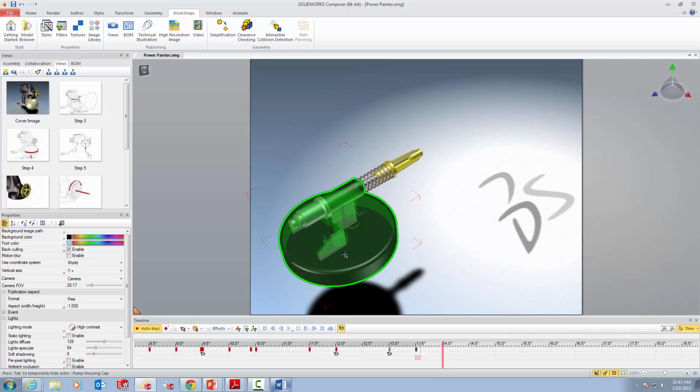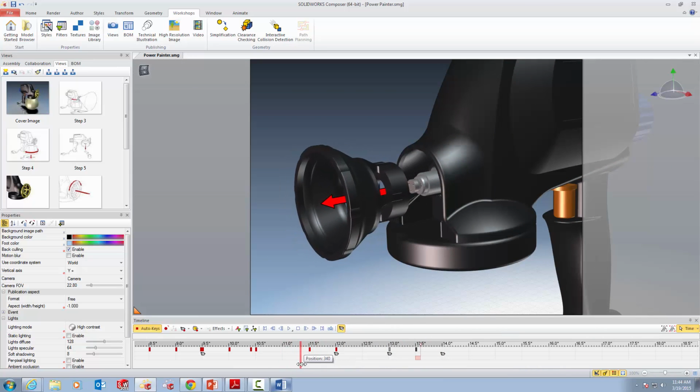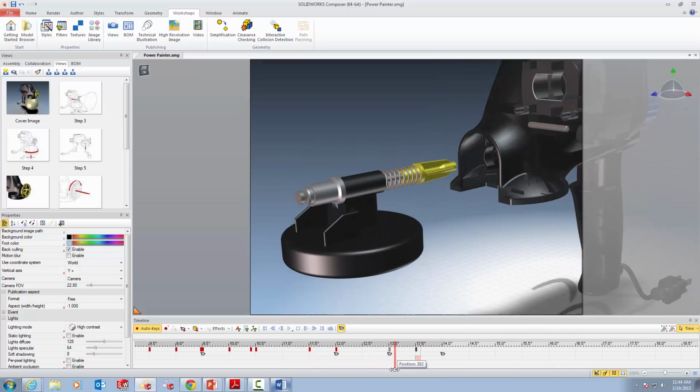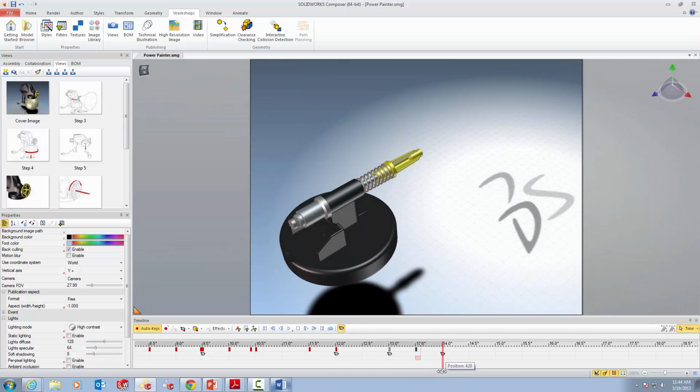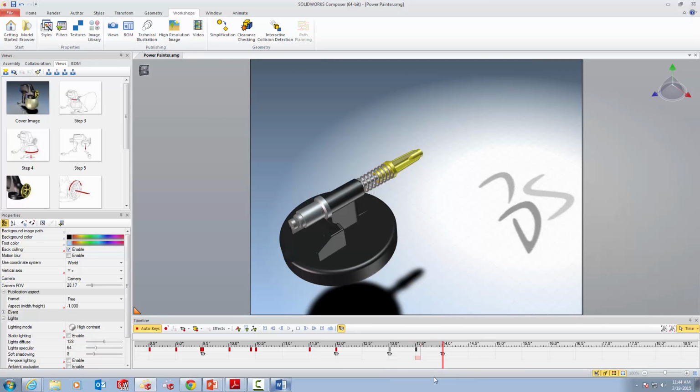And now I'm going to actually select this tool right here called Set Camera Key. Now what Set Camera Key does is it makes a note of its new location. Now what's great about this animation tool is as long as I have this option right here called Camera Play Mode on, I can just scroll right through this and I can see the animation as I build it. So there's no guesswork here. You can see how it translates from here to here, and I just did this with selection of one tool.